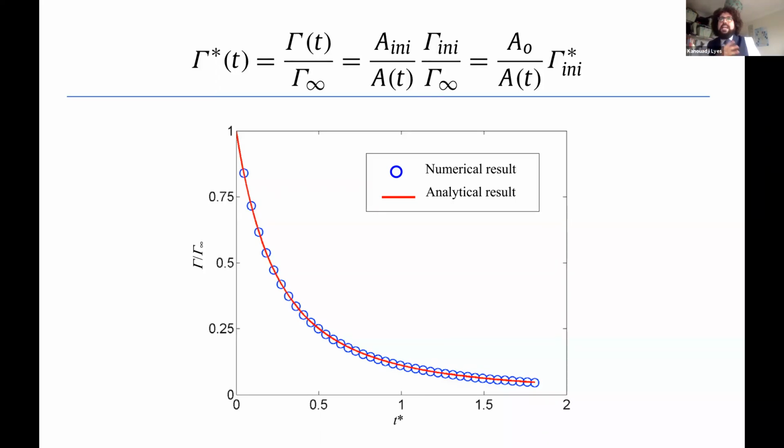What we use here is not a classic front tracking. It's front tracking followed with a level set. A level set is a distance function, positive in one phase and negative in the other phase, and the zero iso-value is the location of the interface.